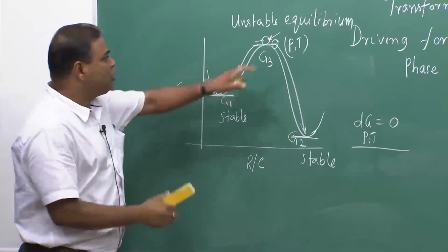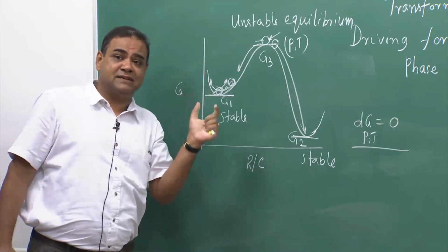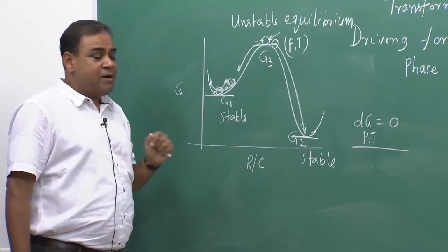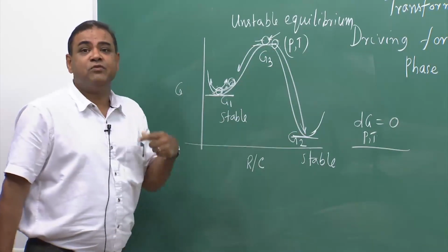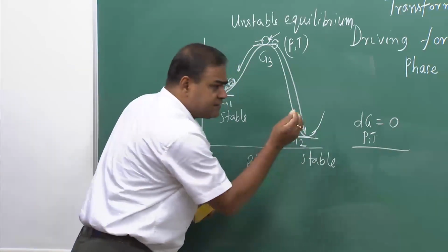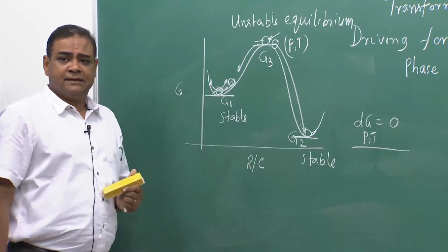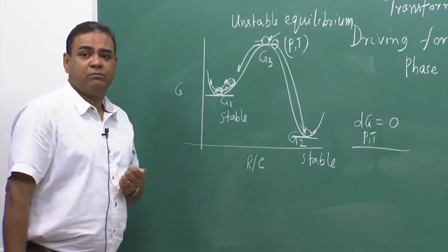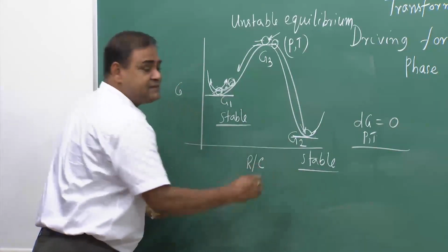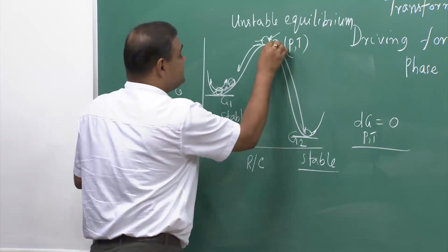Unstable equilibrium. If I do not do anything to this, it will try to maintain that, but it maintains its instability. Whenever I have a little disturbance, it will start dislodging. And in these two positions, they will not go out of the system; if it is a small disturbance, they will go back to this position and stay there. That is why these are called stable positions. But now, do they have the same stability? We will discuss that, but let us come to this point.